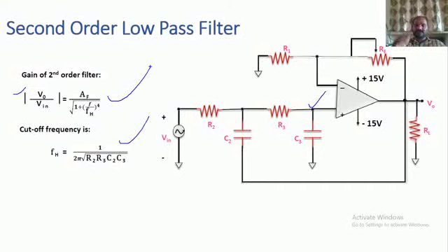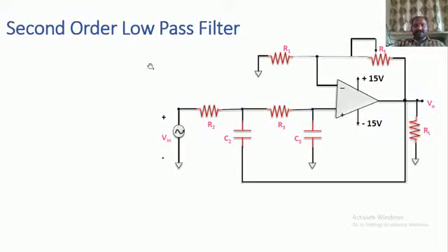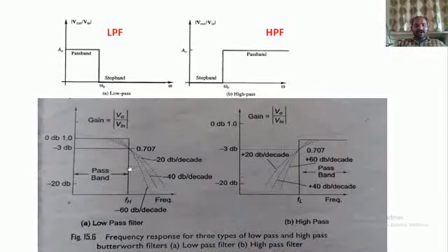So why are we supposed to increase the order of the filter? It means to avoid accepting more frequency components after the cutoff frequency. So this is what we are having. Here we have the ideal characteristics, meaning a sharp cut after the cutoff frequency. We are not expecting any signal as per this particular graph.